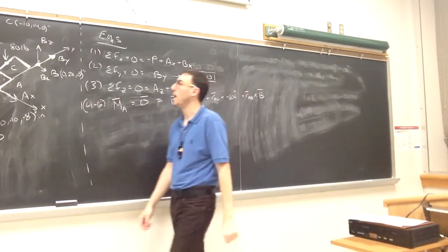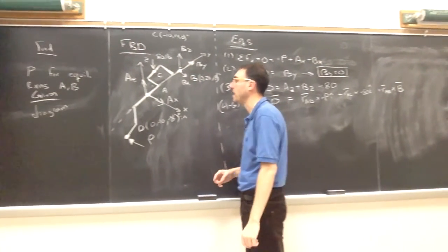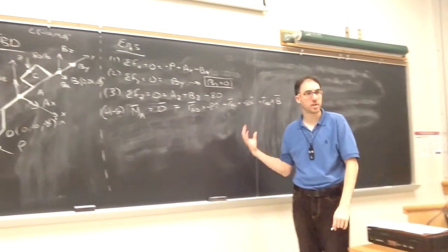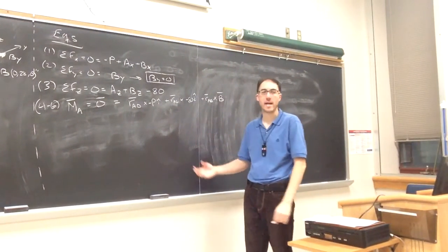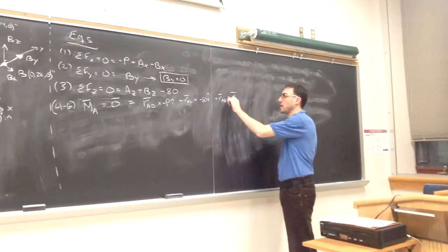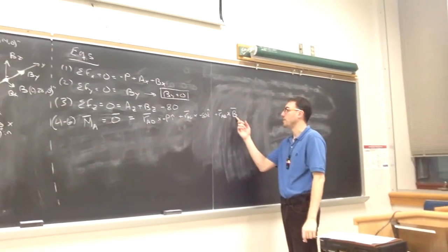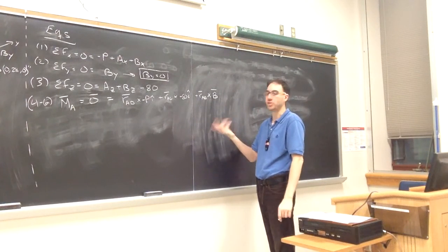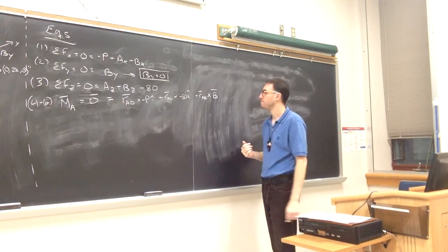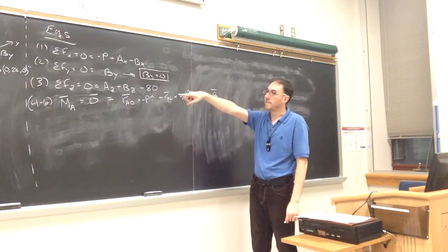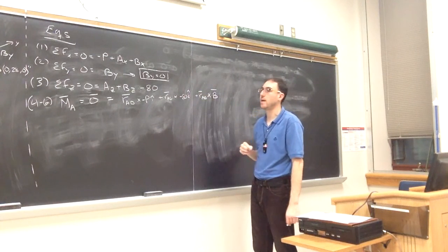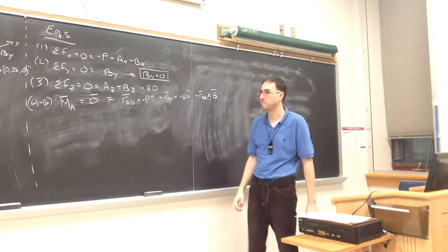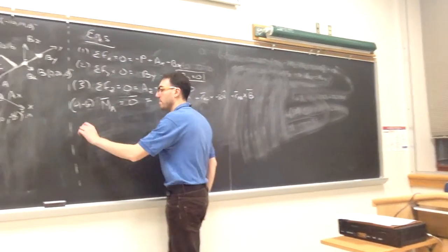Because BX, BY, BZ are all acting at point B, I will just do a single cross product here because I know what component has I, what has J, and what has K. So this is crossed with what I'm calling B, which is the actual force at point B: BXI plus BYJ plus BZK. I've accounted then for the 3 forces that are not at A, so I have to go and make these 3 cross products as my next step.